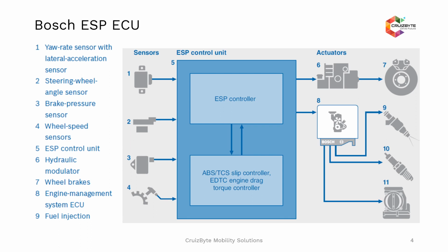These values can be substituted with the help of the Input Output Control by Identifier SID, and momentarily we can take control of, or override, these values from the diagnostic tester, thereby creating some scenario to understand how the observed component is working.